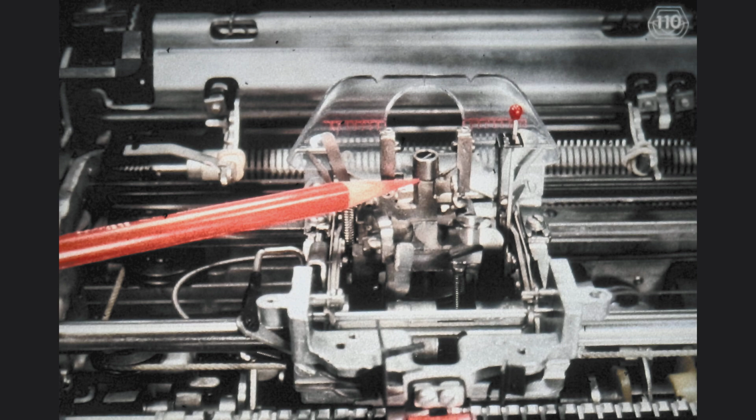This can easily be checked under the lower ball socket, as shown. Since later on we have to adjust the angular position of the rotate pulley, for the time being we just approximate this clearance. When we adjust the angular position of the element with respect to the pulley, that is when we also adjust the vertical position of the rotate pulley, making sure that we meet the 1/10 of 1 millimeter clearance at the indicated spot.